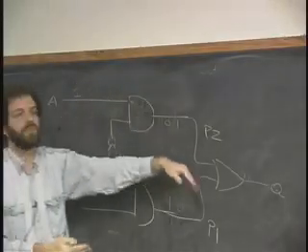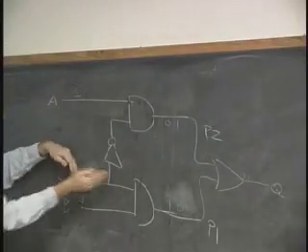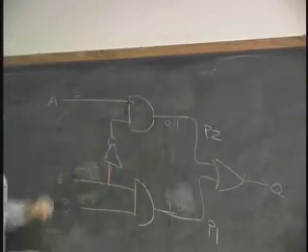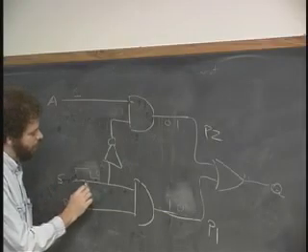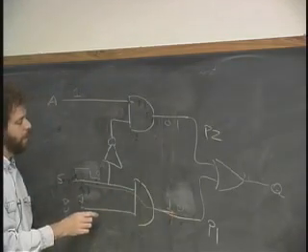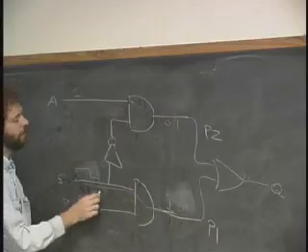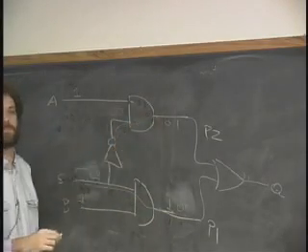And then an OR gate, which combines them all in the big race. Okay? So there's a bunch of mice here, right? And then there's these little gates that let the mice go through. OK, what's the trouble? The trouble is that this path over here to shut off P1 involves less logic than this path over here to turn on P2.